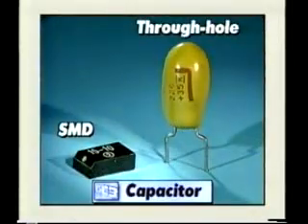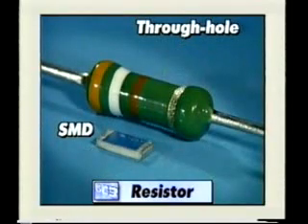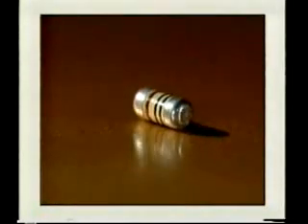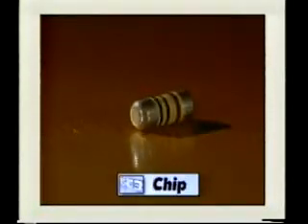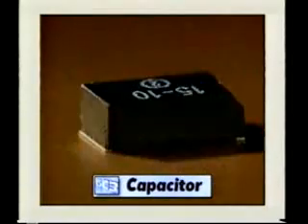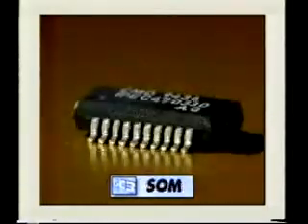Many through-hole components have surface mount equivalents, which are much smaller in size. SMDs don't have long wire leads because they don't attach to holes through the board. Instead, they attach to PWBs in one of two kinds of ways. The first way is with special leads, which allow them to be soldered to a land on the surface of the board.